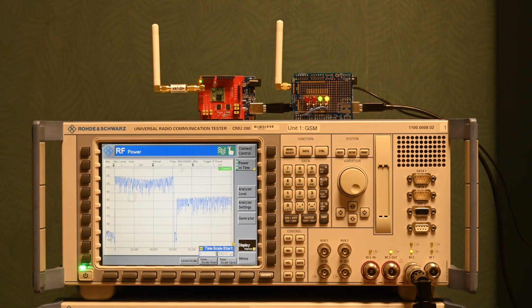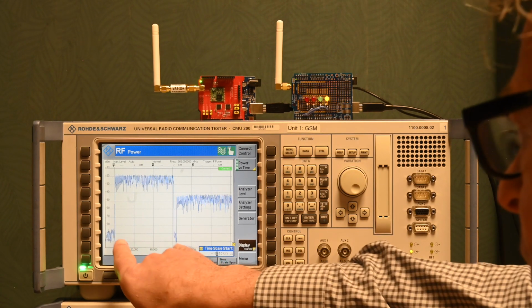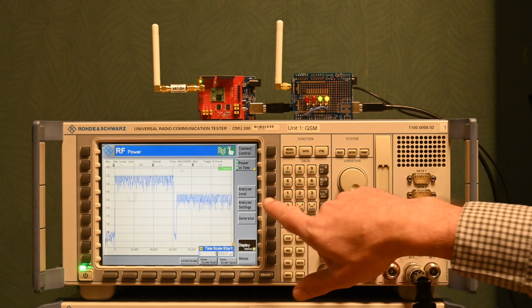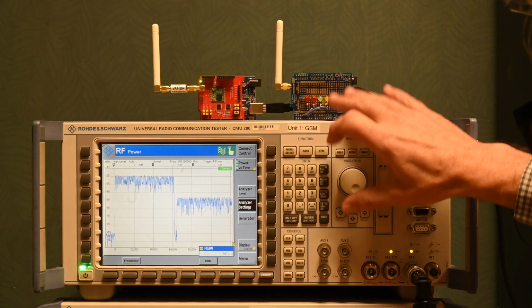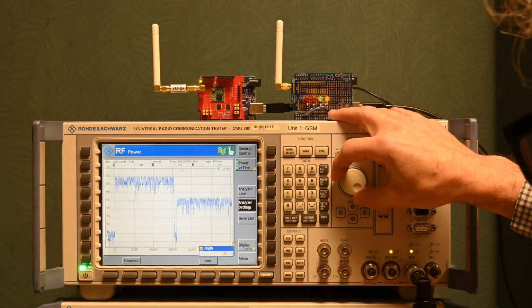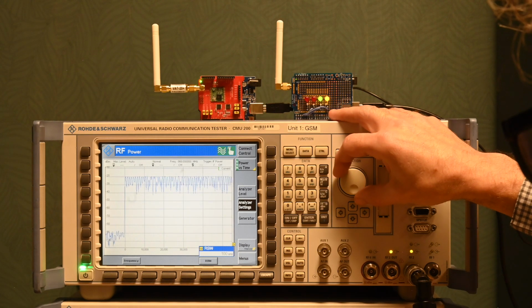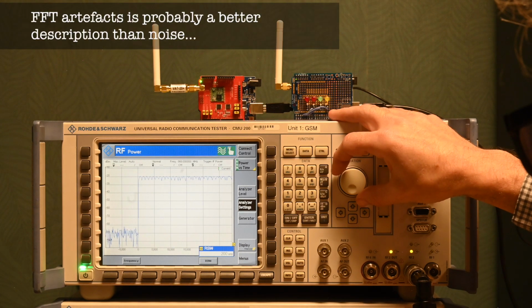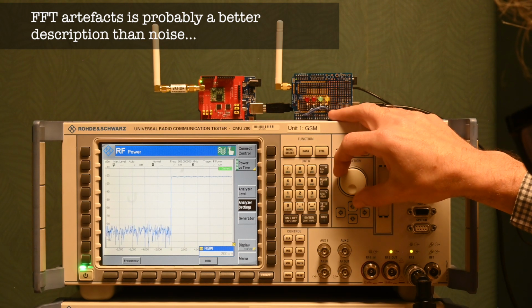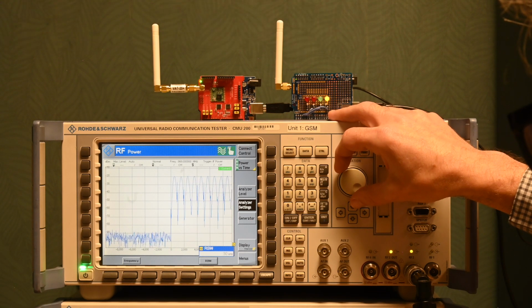So what I actually managed here is to get the full burst of the first unit and then almost the full burst of the second unit in view. You can even look at a longer time period. It comes at a price, however, because if you choose a resolution bandwidth as small as this, what you're basically getting is more and more noise. You can see it happening here. If the bandwidth is high enough, then I get a nice signal. But it does get distorted at the moment that I make it shorter.